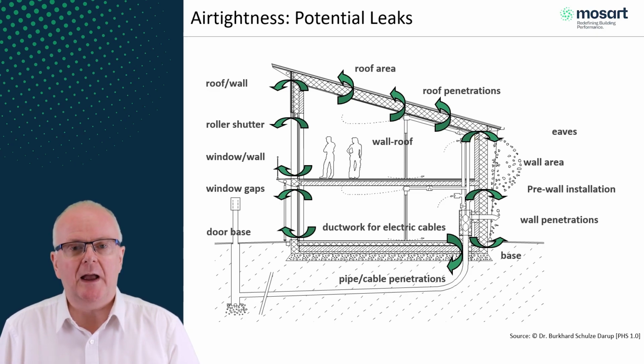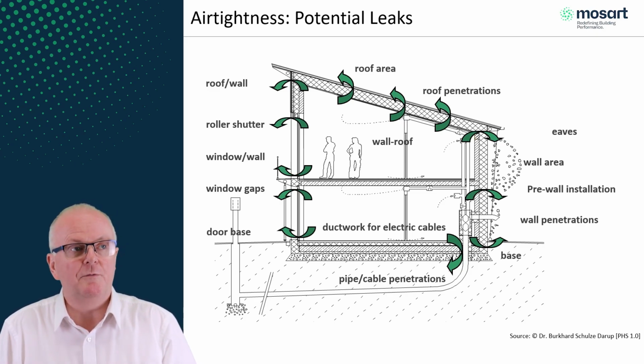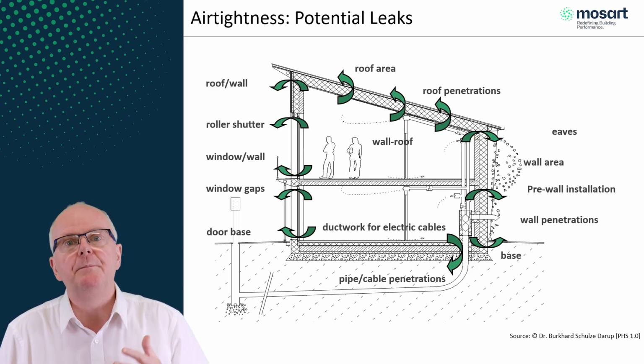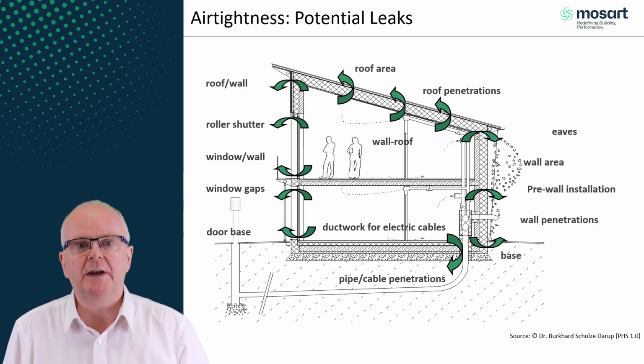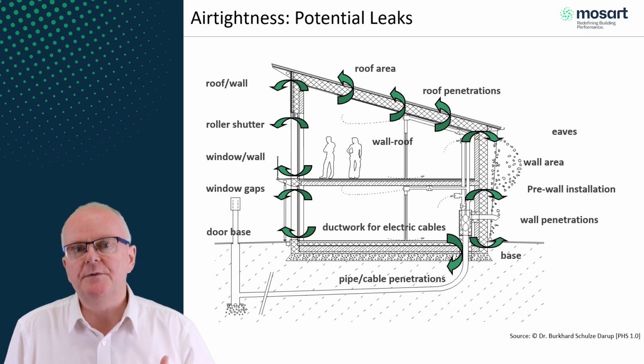Basically anywhere, you're never going to find an air leak, or rarely anyway, in the middle of a wall or the middle of a floor or the middle of a ceiling. It's going to be where you've got an interface or a junction or some sort of penetration like that, okay? So that gives you kind of a good idea as to where you should focus in terms of sealing the